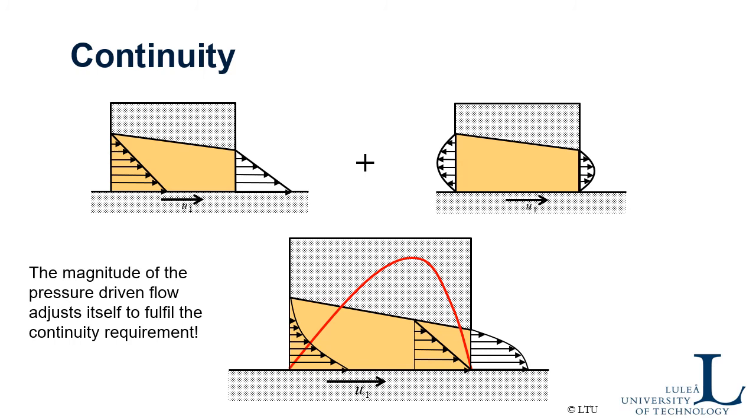So at that position you only have Couette flow, but this Couette flow profile gives you the same flow as in the inlet and in the outlet. So those two natural laws work together with different types of flows, and they balance each other perfectly and create a pressure that normally is big enough to fully separate the surfaces and create a very good lubricating film.